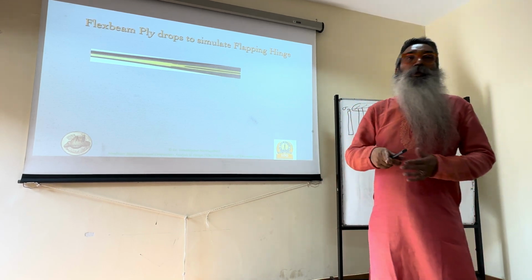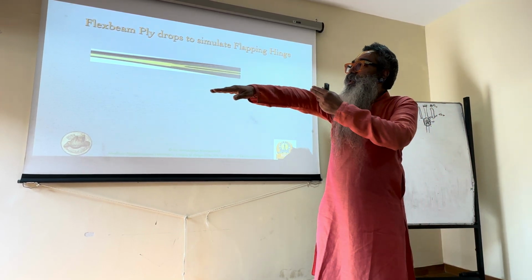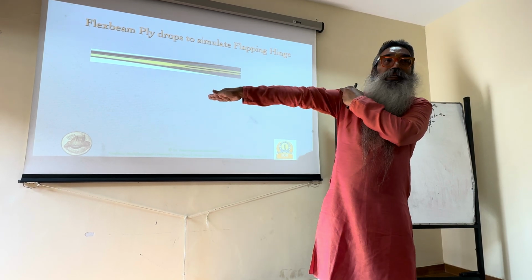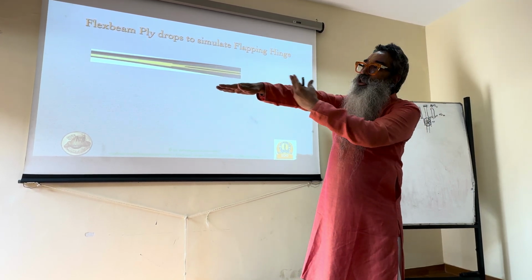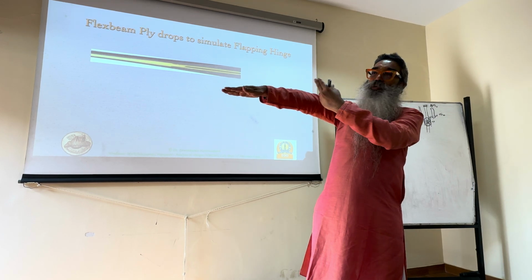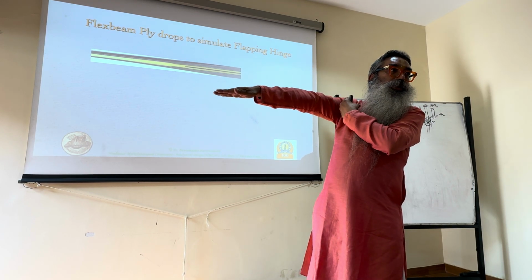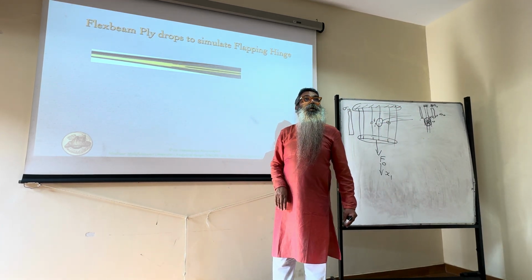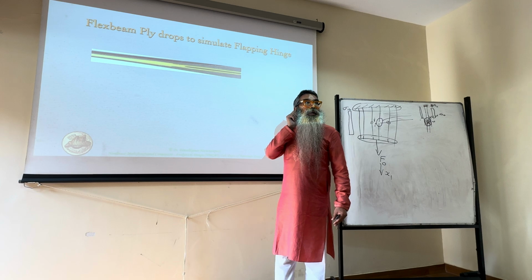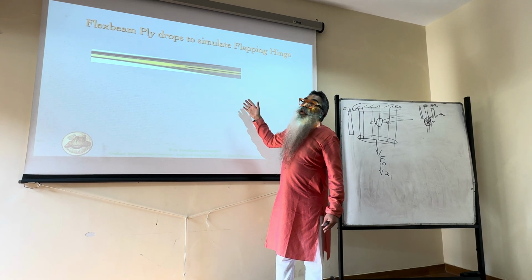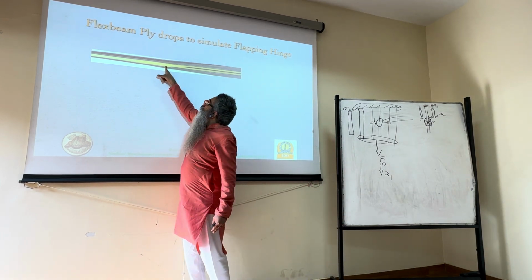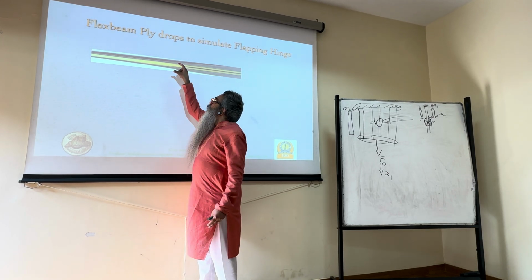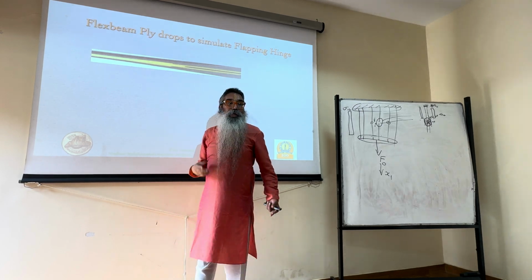taking the shear loads. Because of the lift distribution and drag distribution, there's not only a bending moment in the two directions, bending this way, but also a shear force. So if you draw the shear force diagram, you'll see there are certain locations where the shear force becomes very large, which is closer to the root or the hub where the helicopter rotor blade is attached, and there you would see that you have this kind of a geometry will help to take the shear loads through the glass fibers and the extension, compression, bending, flexural loads because of the carbon fibers.